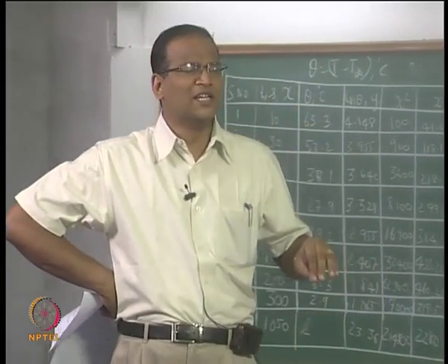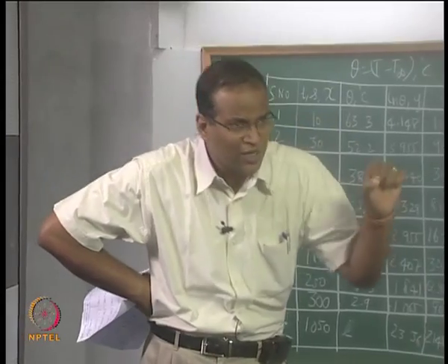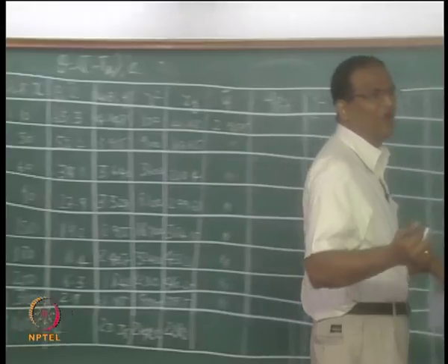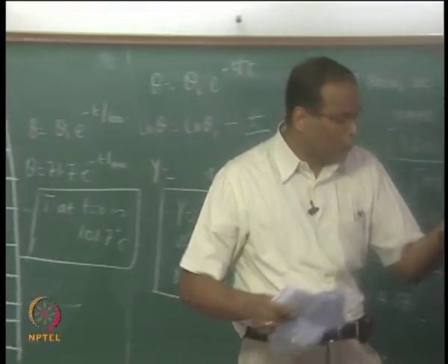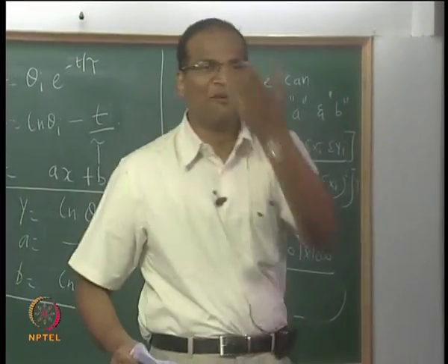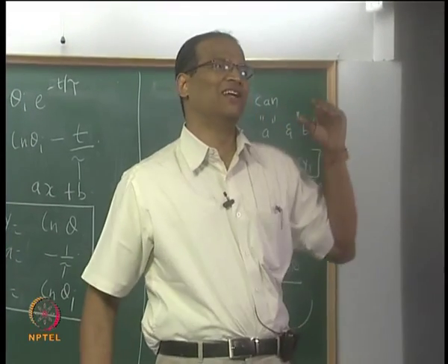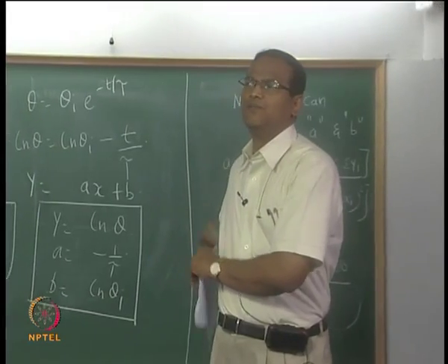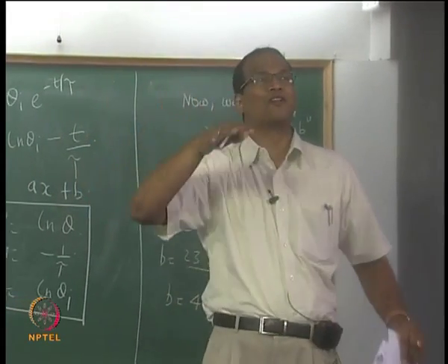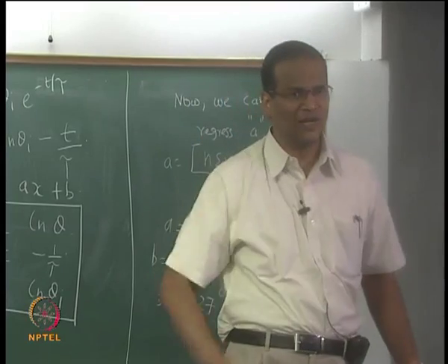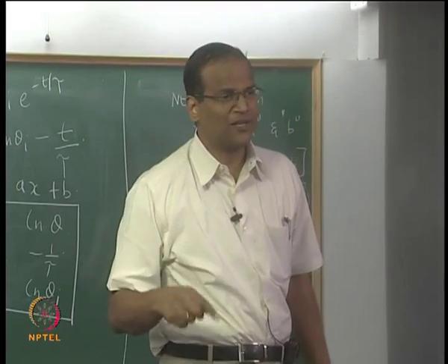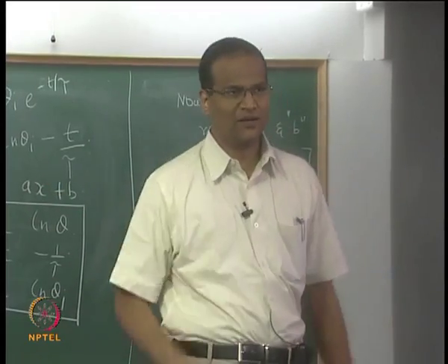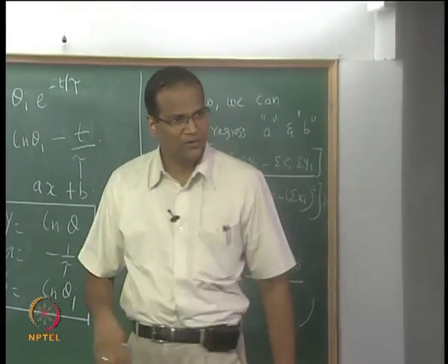It is very difficult to measure the initial temperature exactly when you are trying to measure, already 1 second has elapsed, right. How good is your time constant? When you look at the stopwatch and try to look at the thermometer, that 0 is the critical point, so we will leave. So normally because we are having so many data points, it is possible for us not only to retrieve tau, it is also possible for us to retrieve theta I. Then you have an additional measurement, suppose it says 100 degrees or 100.5 or something, and this says 101, it is all right. So they are of same order, all right.